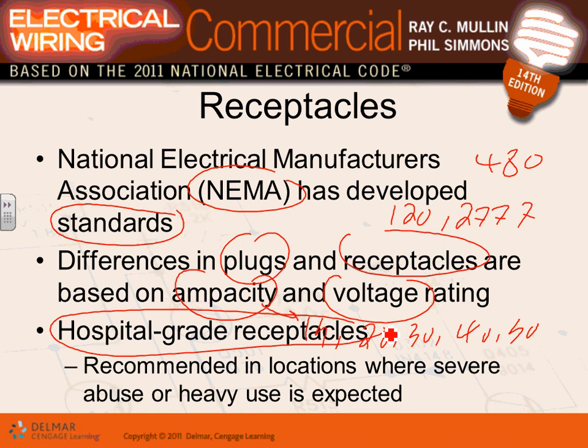There are 3 types of receptacle that we use in the industry, guys. For the most part, we have the residential type receptacles, so cheap, 33 cents. Then they have tamper-proof now; the tamper-proof receptacle will probably run you $1.20 or something. Then we have the commercial grade type receptacle. It's more robust, stronger, bigger. If you go to Home Depot or Menards, you'll find they run you a couple of dollars versus $1. And then there's the hospital grade receptacle. Again, they are more robust. They have to be identified as hospital grade because of use and severe abuse.